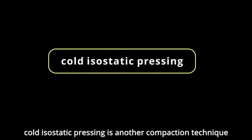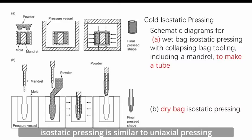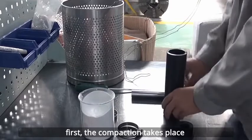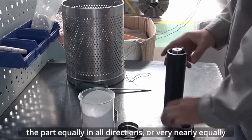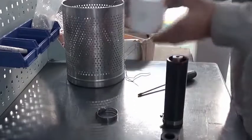Cold isostatic pressing is another compaction technique. Isostatic pressing is similar to uniaxial pressing in the requirements for the powder and in the general step of the press. But there are several important differences. First, the compaction takes place under hydrostatic conditions. That is, the pressure is transmitted to the part equally in all directions, or very nearly equally.